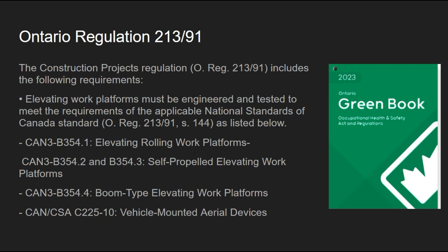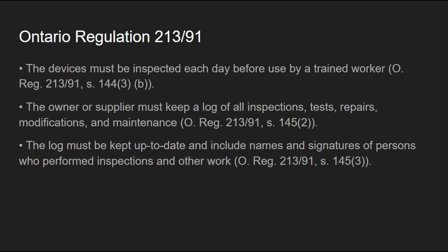Regulations. There's different papers on each type of lift that you're going to use. And elevated work platforms must be engineered and tested to meet the requirements of the national standards of Canada. This is a larger device, so you've got to remember, it's got to be inspected each day before use, and it's got to be inspected by someone who knows what to look for on the inspection.